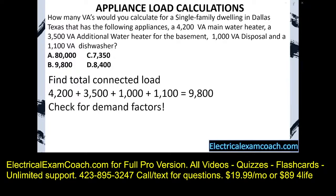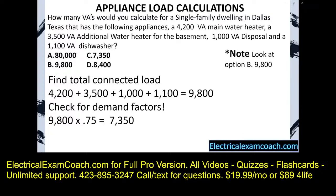Now, we check for demand factors. Sure enough, we have 4 or more fixed appliances, so we can apply the 75% rule. We take 9,800 multiplied by 0.75. That gives us a new reduced load of 7,350 VAs. I want to note that if you look at option B, it was 9,800, as if you didn't apply the 75% rule. You've got to be careful.